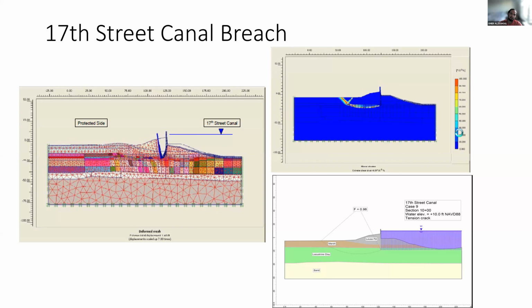Because the levee was built on a marshland, the clay below the main body of the levee was compacted and consolidated, but at the top it was still normally consolidated. So the difference of the shear with the high water pressure started to push on the clay below the levee, which caused the shear failure and pushed the marsh. After the hurricane, they found pieces of the marsh clay layer pushed away from the site. And then the whole segment failed.